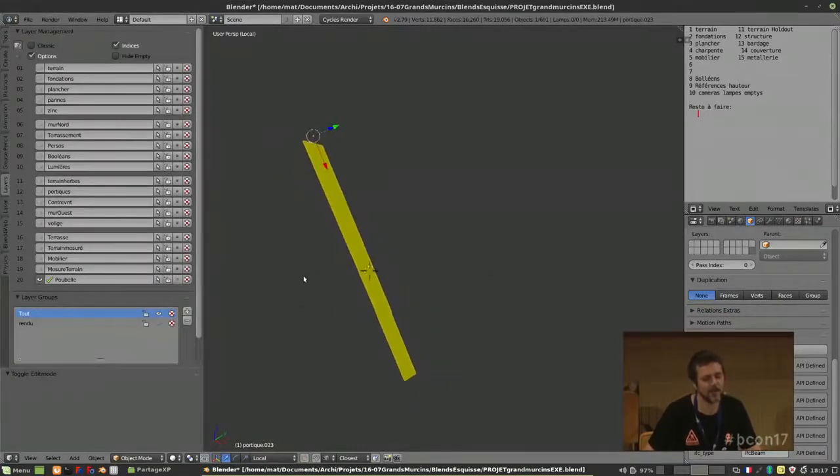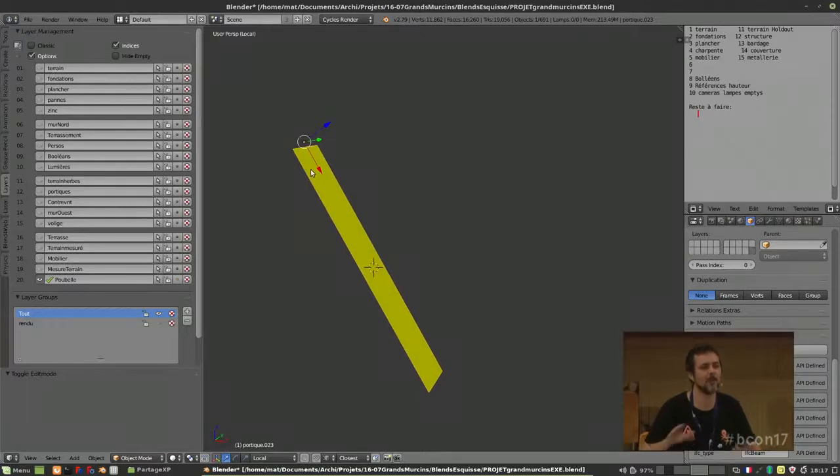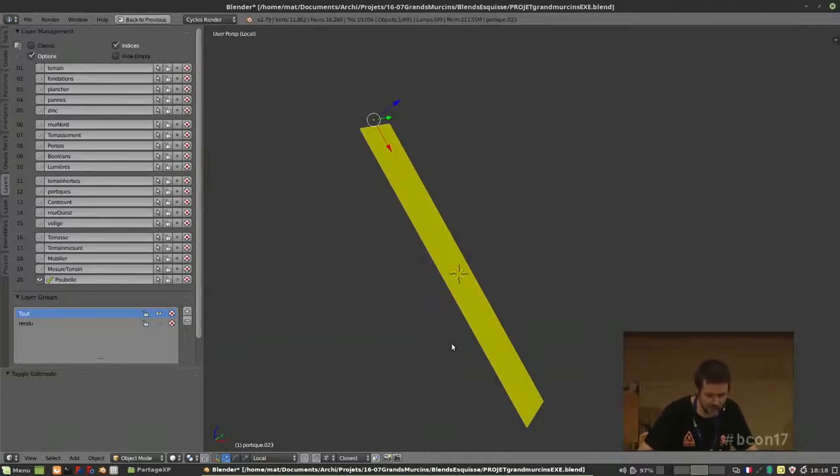The problem is that the IFC exporter exported with the Z axis this way. So if you want a 2D curve, you will lose, because the 2D curve has the Z-axis normal to the surface. If you want a 2D curve so that you can afterwards add some thickness with the extrude, so that you can check that your model is correct. If it's not clear, I'll show you.